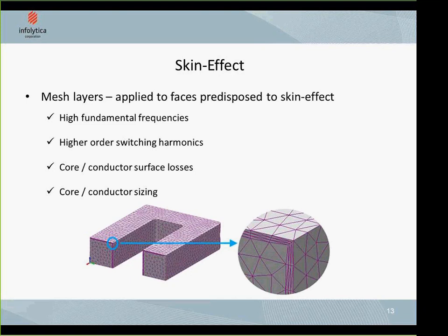and the core is also the same. So if you're working with high fundamental frequencies or you have high order switching harmonics, you may want to estimate your conductor losses. And it's also a good thing to be able to estimate your conductor sizing, so to know how much you want to strand your coils or to size your core. In this case, to size your magnetic core.